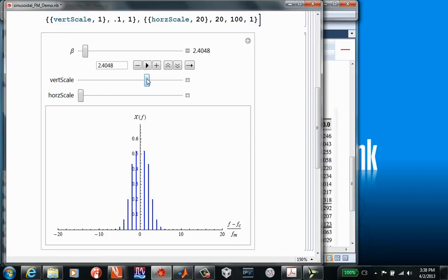Suppose I wanted you to call out a value you want to verify, just to see if the plot comes out right. What's another sideband you'd like to see go to 0, either the first or the second time, from the chart? 8.317? Okay, 8.317. Is that right? 8.317. Okay, so that's putting the next pair of sidebands to 0.